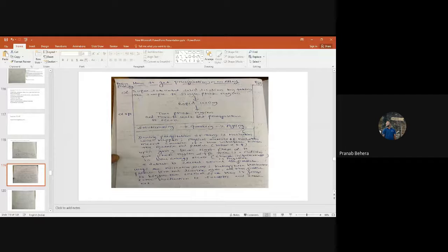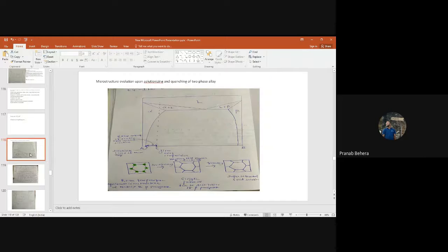Sir, what is the benefit here? Because we have our precipitate in our first stage, later on we are getting the same precipitates. So what is the benefit? The benefit is that these precipitates may not be uniformly distributed when you are doing melting and casting. You are making an alloy, at the end you are doing melting and casting, right? You'll get a cast product, for example. In that cast product, it doesn't mean that all the precipitates are of uniform size, all of smaller size, which you want, the desirable size, or that the distribution of precipitate is the same everywhere. You understand now?